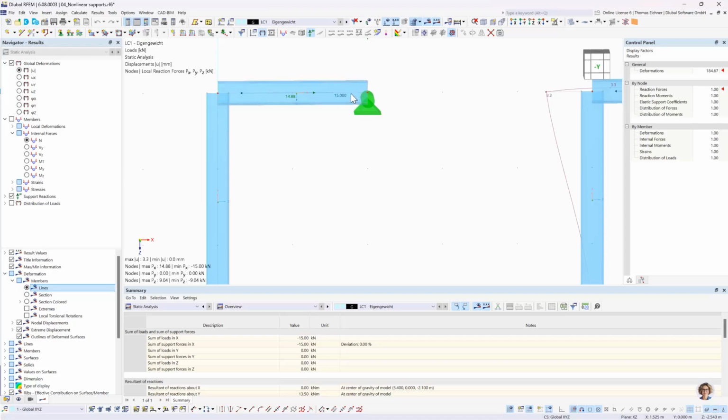and the force that really comes to that support would point in negative x direction, like the force we applied here. You see this 15 kilonewton? It's directed in negative x direction. So there will be a force to that support in negative x direction, and for that support to be able to withstand, or to have zero deformation, it needs to have a reaction force in the other direction. That's why this reaction force is defined in positive.